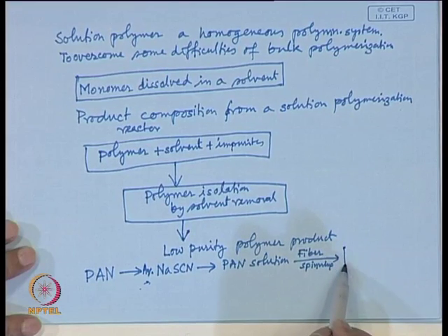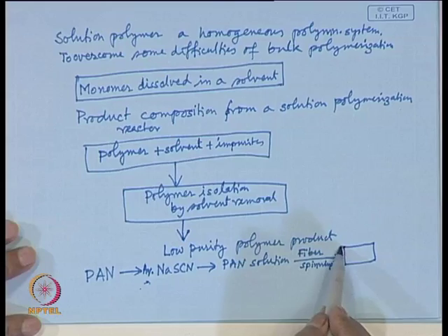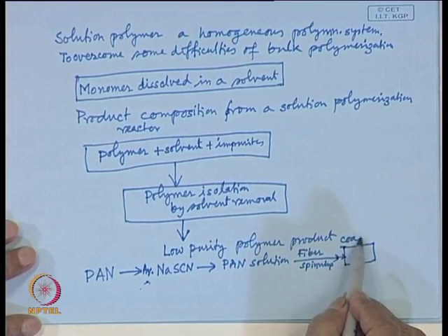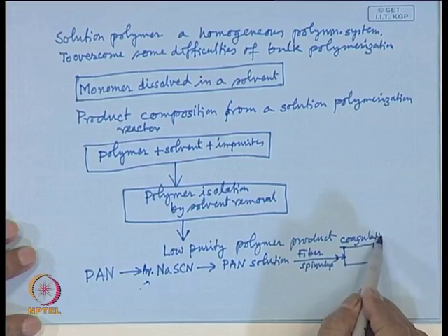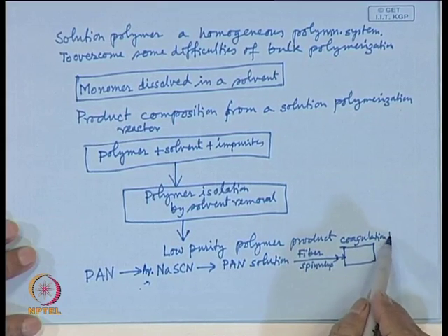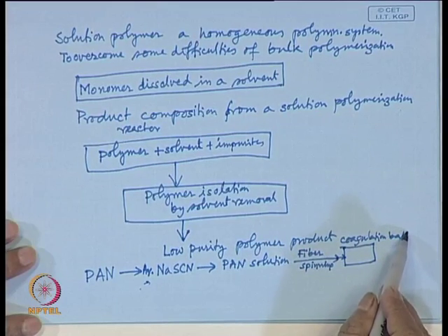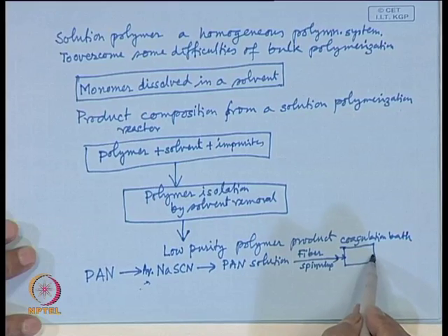Actually, it passes through a coagulation bath. This is a coagulation bath. The fiber gets coagulated, and we get PAN fiber.